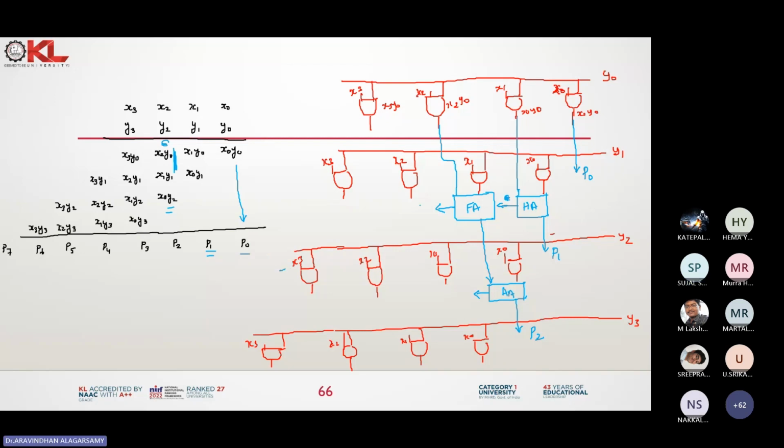Yes, sir. Right. So if that is the case, what will happen to the next stage? Now with these logics, we can draw easily. How can we draw easily? Because there are carries coming from your previous stage, it is not going to become a half adder. It will become a full adder. This has to be added over here. This addition becomes a half adder. The carry is going to propagate into the next stage. So this full adder can be given over here. One carry is already propagating from your previous stage here. This becomes a full adder, and this is going to come out.